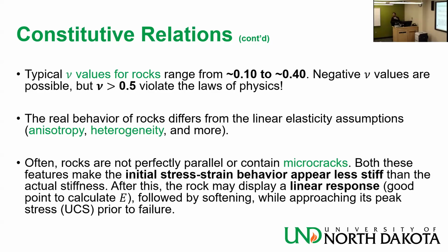Some of those defects are making the material misbehave. It appears that it's softer than what it really is, because I'm basically creating motion or deformation by closing those microcracks. I'm not compressing the actual solid. I'm just compressing air out of those cracks and closing them down. So if you're doing experiments, don't believe what the machine is telling you, or even what the data is telling you. Think about it. It's trying to tell you something.